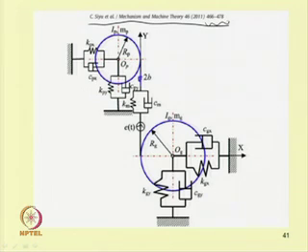So, here the backlash and clearance are taken into account. By taking the backlash and clearance in a gear system, one can write the equation of motion. One can take this spring as a nonlinear spring also. So, one can write the equation of motion of the system, and solve these equations using the methods studied today.